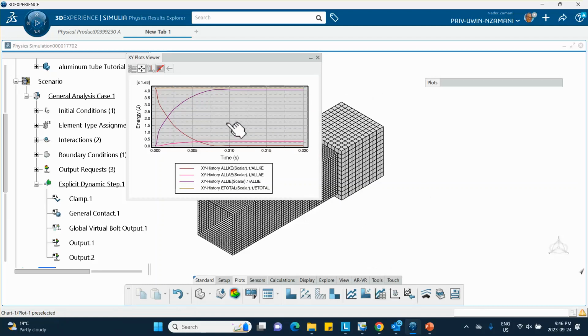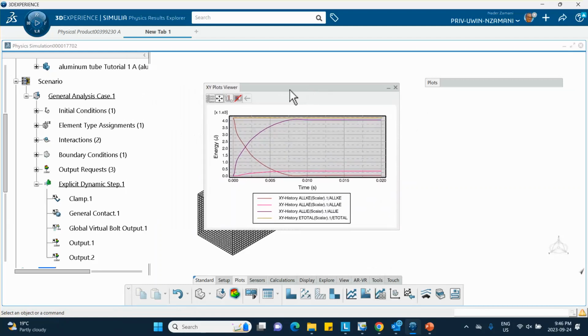So in the future, in some other tutorials, I will change that block, which I meshed with solid elements, into shell elements, and then later on we do it with a rigid analytical surface. So this problem is going to be done three different ways. The indenter is a solid object, the indenter is a plate, and finally the indenter is an analytical rigid surface. Okay, and that takes care of the first tutorial. Good luck.